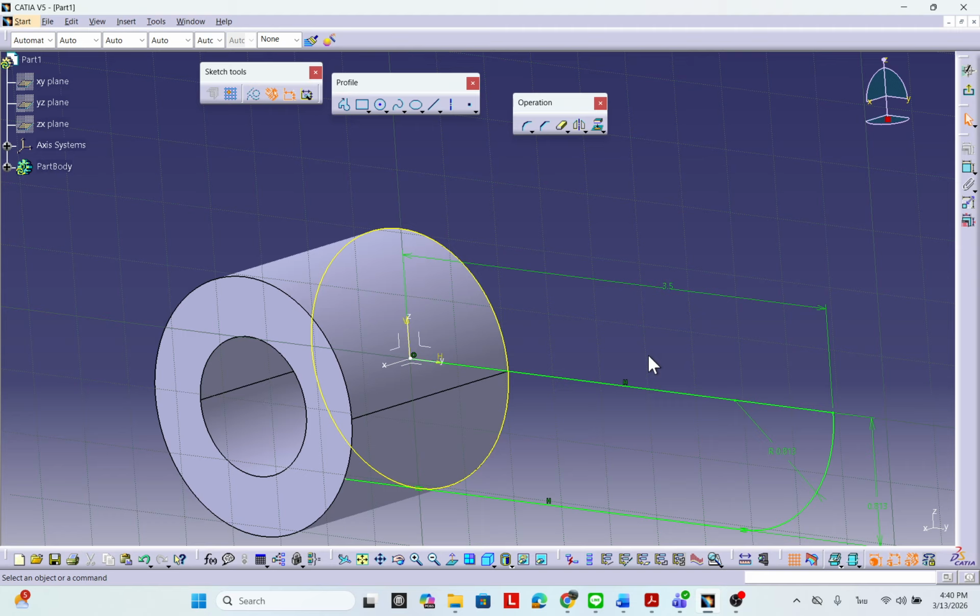Maybe you change the sketch of the cylindrical part, right? Change the diameter, and the yellow color is changed as well. And that means associated, right? If you don't need them associated with each other, maybe you need to set the yellow color independent of the cylindrical part, because when the solid is changed, the line still stays here. It doesn't change anything, it's still something like that.